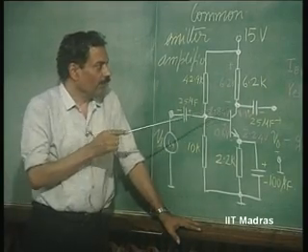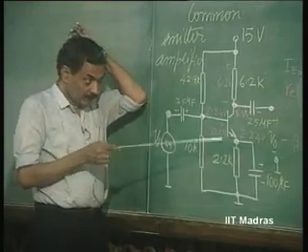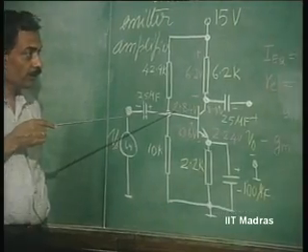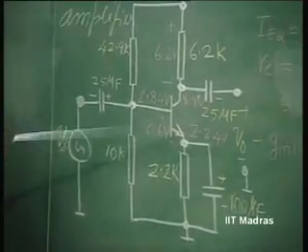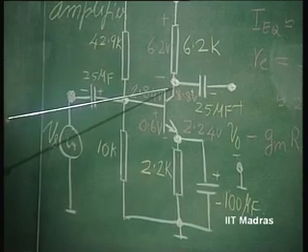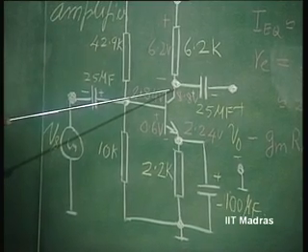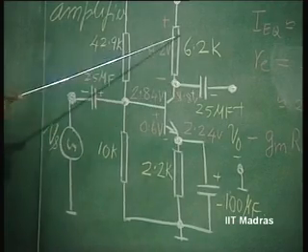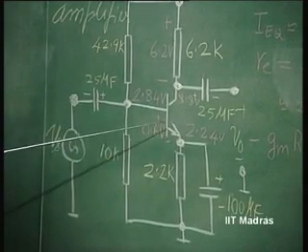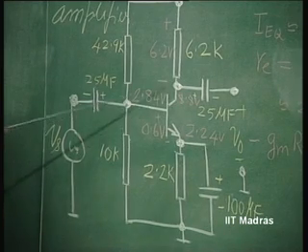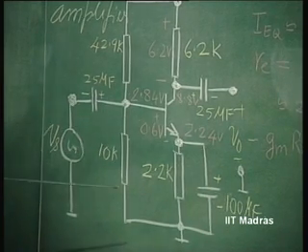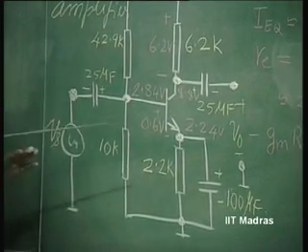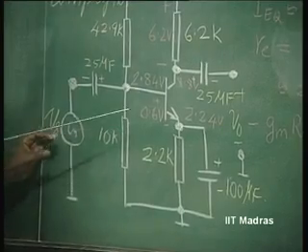Now we will illustrate the large signal effect. Now that this is biased to VCBQ of 6 volts, and the current I is about 1 milliampere, there are limits. One is the transistor going off: that 1 milliampere into 6.2 K is 6.2 volts on one side, and on the other side it is again 6 volts. It is almost a symmetric swing. That means both the saturation limit as well as the cutoff limit should begin almost simultaneously. So let us keep increasing the signal.